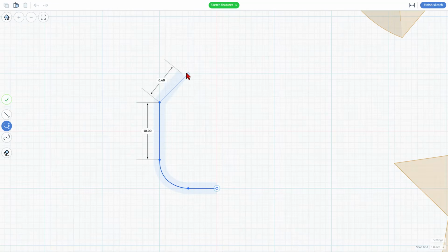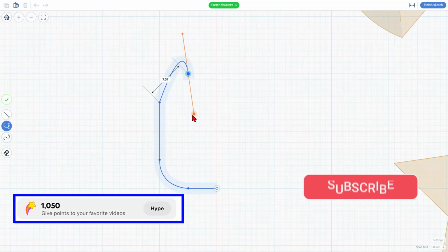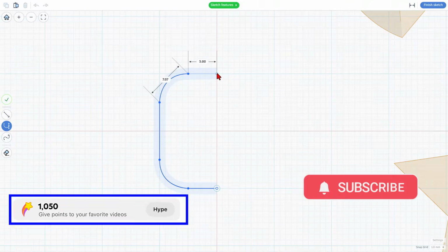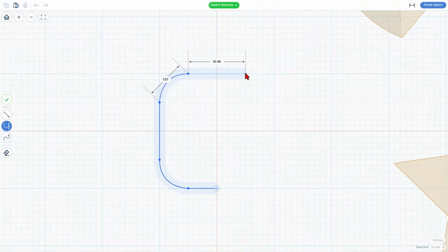We're still in the Bezier curve mode, so if we go 5 over, 5 up, click, hold, and twist, but just twist it till it's straight with that line. See how those dots lined up exactly? It is that easy to make a perfect curve. Once again, 10 across, 5 over, 5 down, click, hold, and twist, snap to the exact measurement.